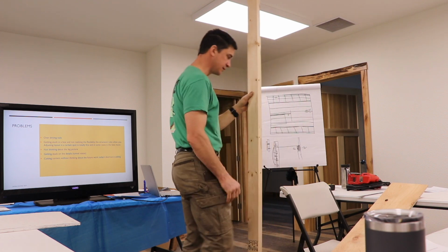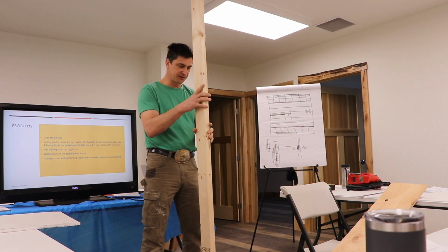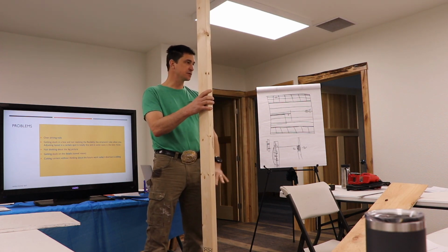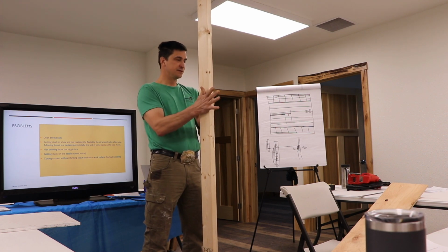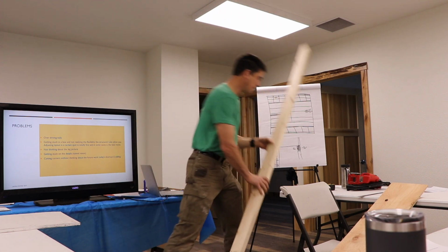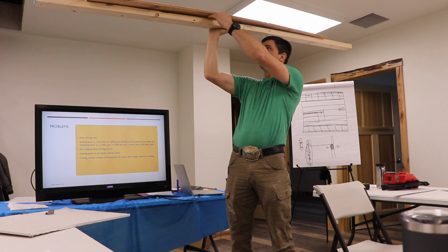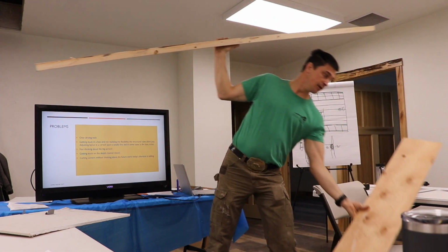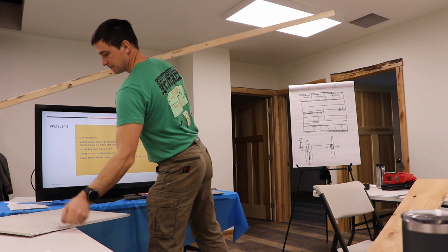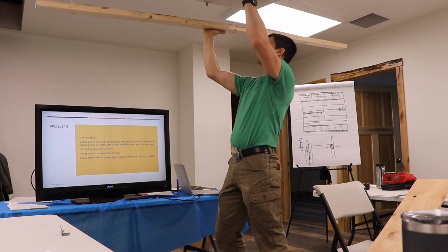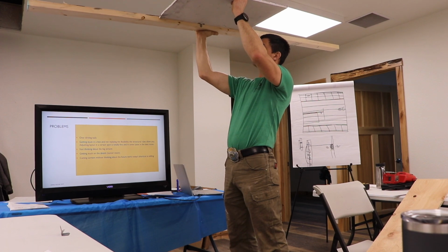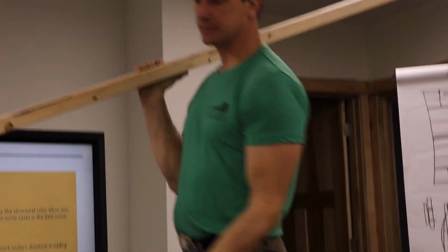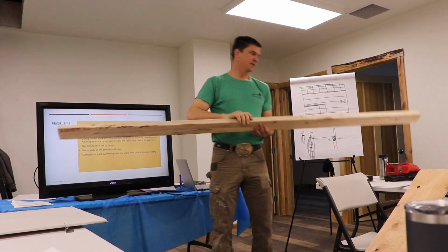What I want to see is this end stud, then our other wall is here. We'll put ladder blocking, like 3 blocks in here, so every 2 feet you have a block. So it holds the stud straight. Then hold the end of that drywall, and then your wall sheathing bumps into that. We would say, let's just leave this off. When we run our ceiling drywall in, it just gets a screw or a nail through that clip at the end wall to hold it in place. Yeah, definitely less bulky. It's so fast.